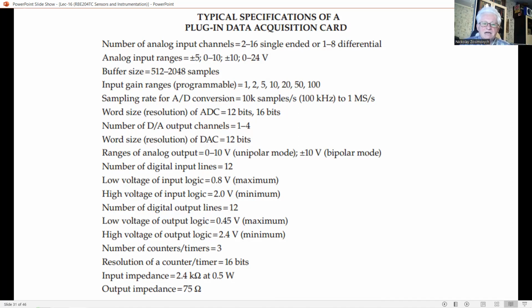This is the rate at which an analog input signal is sampled by the ADC. The Nyquist frequency, or the bandwidth limit of the sampled data, would be half this number. For a sampling rate of 100 kS/s, it is 50 kilohertz.